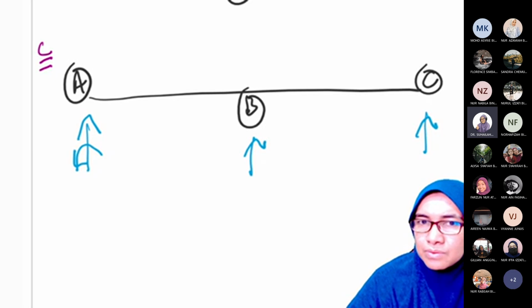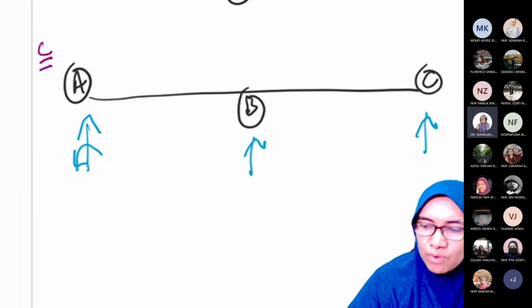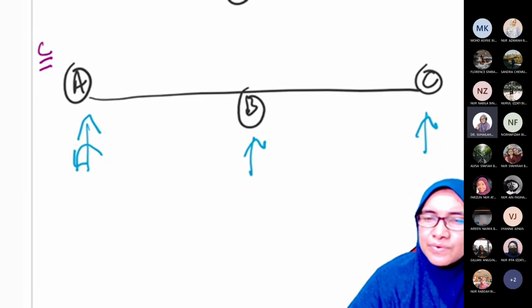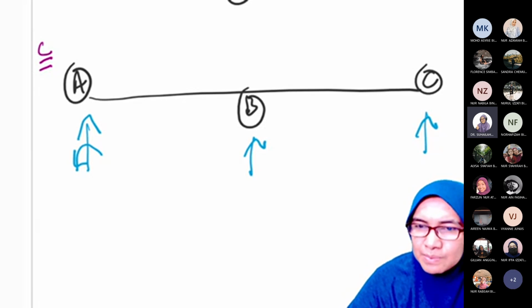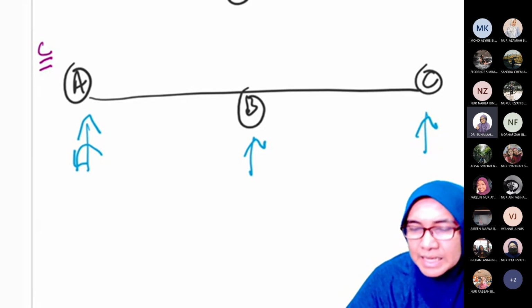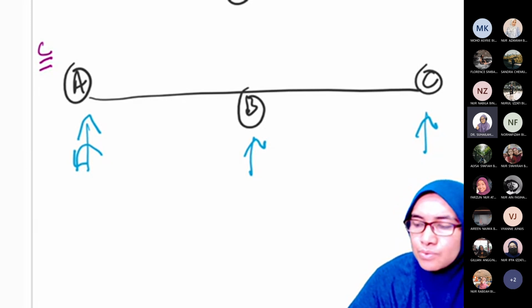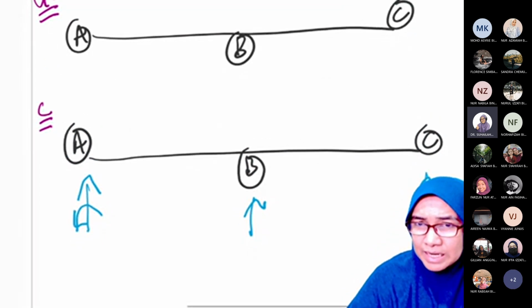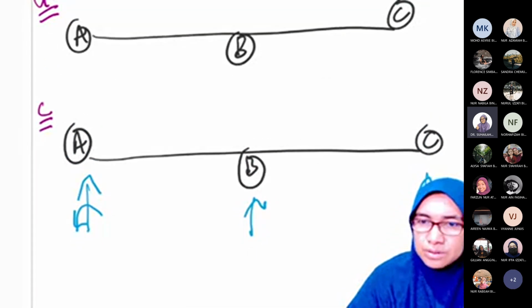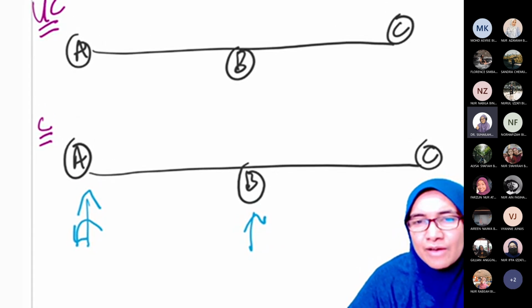But we don't count X in at fixed support, so we minus by 1. So that is why we get 4. This is 4 unknown reactions, which represent 4 degrees of freedom in the constrained system. In total we should have 6 degrees of freedom because there are 3 nodes, and we should complete the 2 DOF per node.